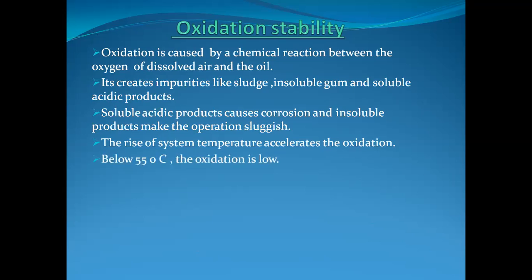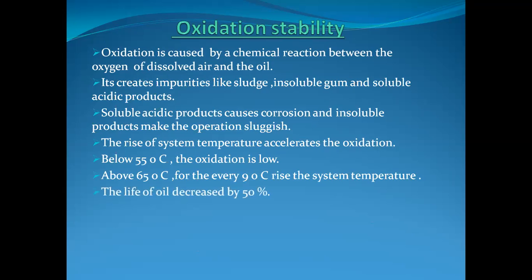Therefore, the temperature must be maintained in the system at a particular level. What happens if the temperature changes? Below 55 degrees Celsius, the oxidation is low. And above 65 degrees, what happens? For every 9 degrees Celsius rise in the system temperature, the life of the oil is decreased by 50%.